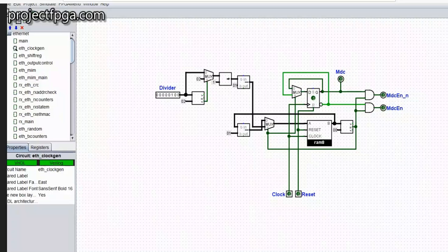So what does this do? Whenever it comes on, so for every time it gets down to 0, this multiplexer keeps switching between 0 and 1, 0 and 1, thereby generating the clock. This is the opposite, the negative of what it has. So this divider determines how long it takes for this clock to change, therefore generating the new clocking frequency.